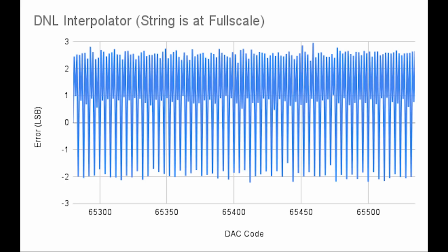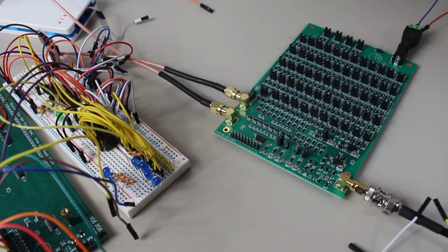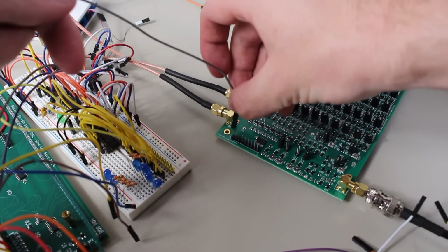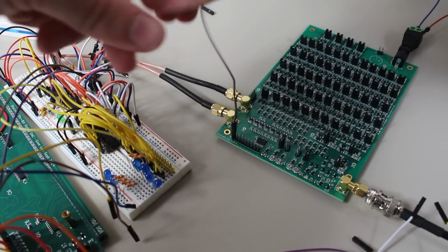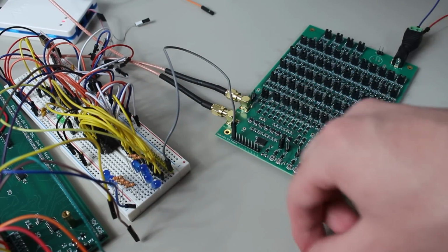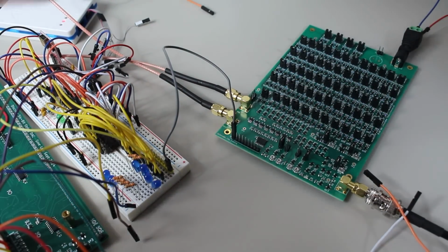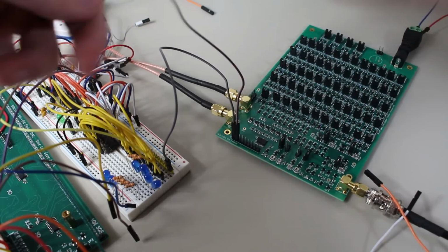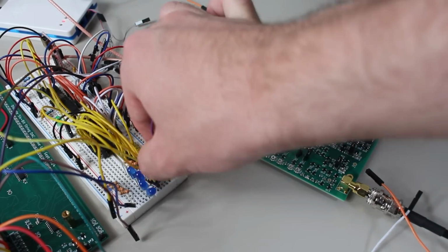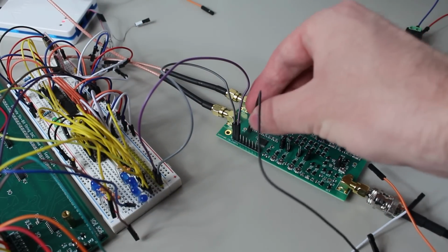But why is it like this? Well, remember our discussion on the matching of the differential pairs? It occurred to me, after putting this together, that while the degeneration solved many of the problems with matching the transconductance values, it did not completely solve the problems with matching the gate threshold voltages. You'll also see that the pattern occurs pretty often. This means that the lower bits of the DAC are contributing the most to it. The upper bits also have problems matching with each other, but they also have multiple pairs per bit, which means that the matching error gets averaged out.